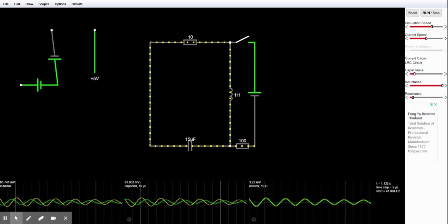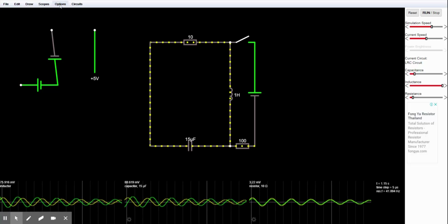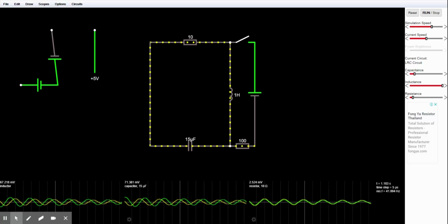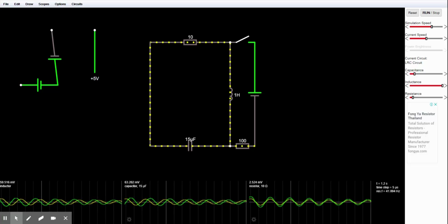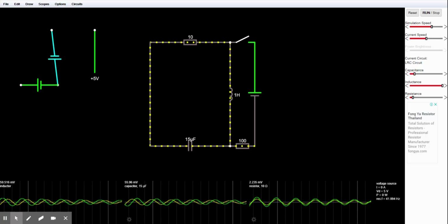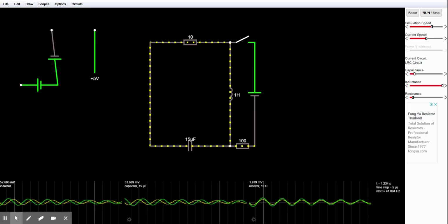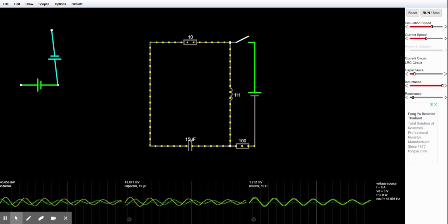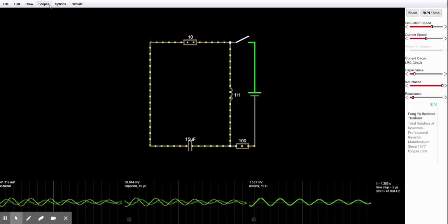So this is understood. Typically, unless we are making an op-amp circuit where there are various connections to the battery, we will usually use the 2-terminal source. Okay, if you want to delete it, select it and press delete on your keyboard.